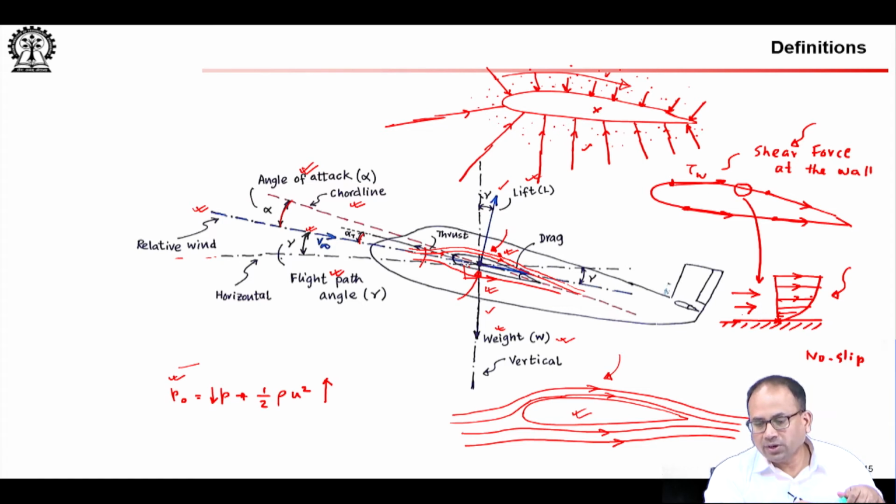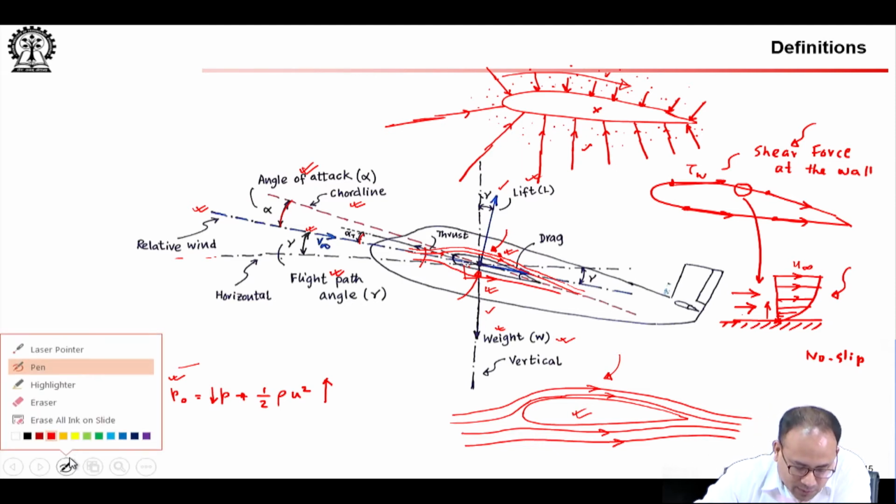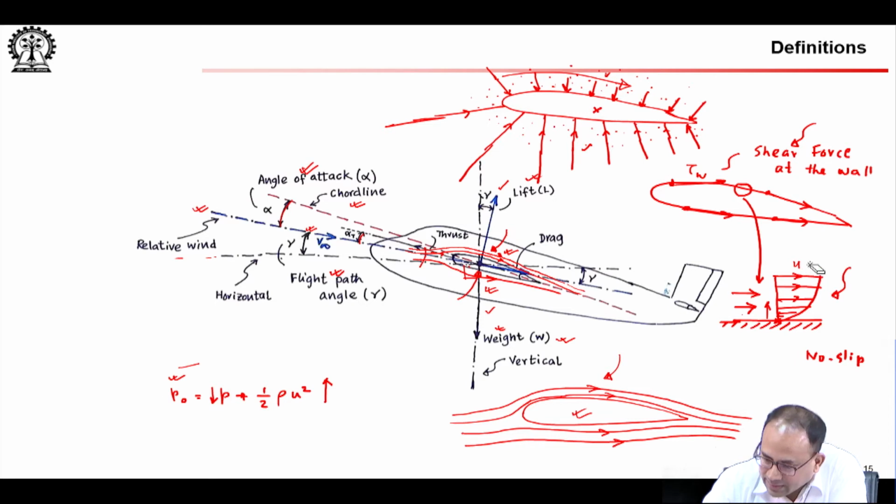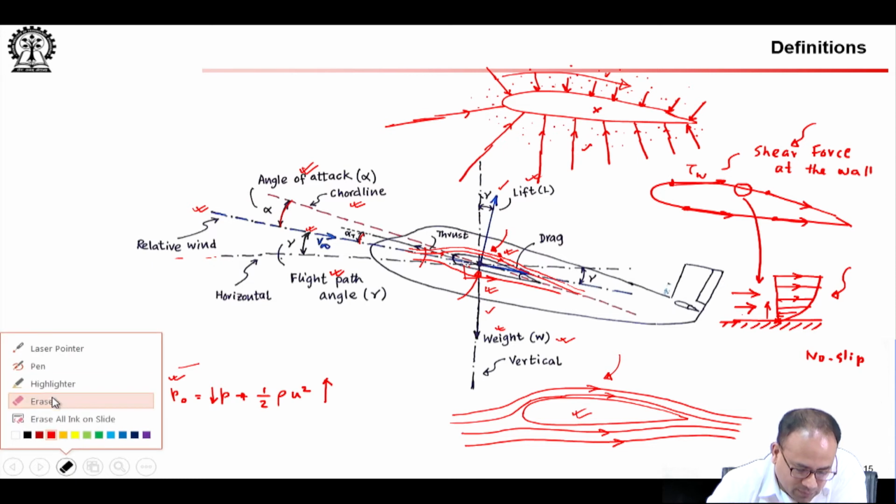So, its horizontal velocity component, or the velocity component parallel to the wall, of course, normal to the wall, it is not a porous wall here. So, the normal component is 0 and the tangential component of velocity parallel to the wall also becomes 0 at the wall. As you go away from the wall towards the free stream, suppose the free stream velocity is u infinity. So, beyond this you almost become u infinity. I say almost because it does it asymptotically. Okay. So, it goes from 0 to u infinity.